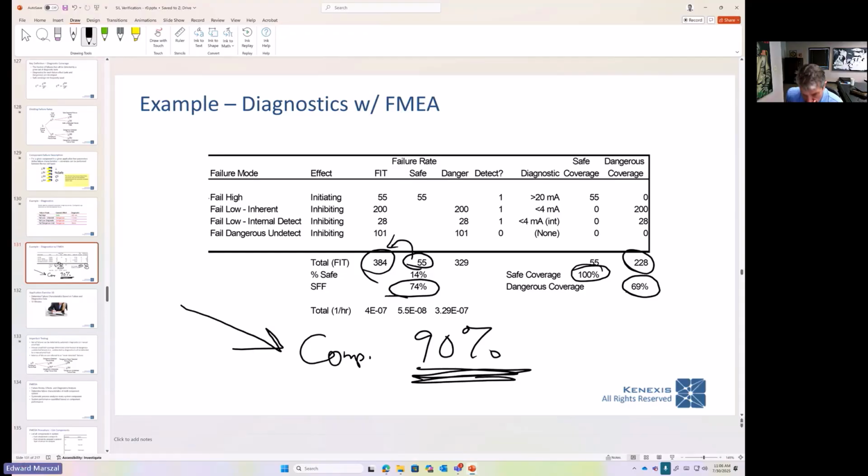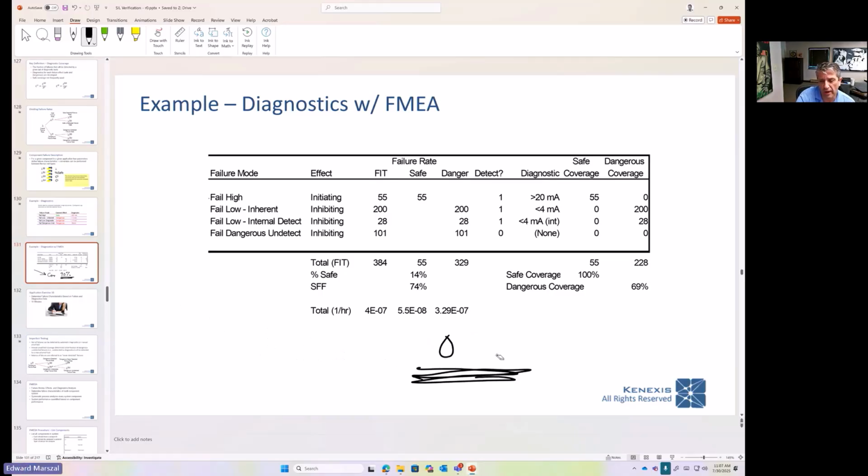Okay. And the second doubt is in the example of your pressure transmitter, there was only one sensor, a 1 out of 1. Is it possible to have an internal diagnostic with only one sensor? Because in the table that you have shown from the IEC 61508, the input comparison is always talking about 1 out of 2, 2 out of 3, or better redundancy. Could you show this table? In your example, you have only used one sensor, 1 out of 1. With one sensor, could you have internal diagnostic? I guess yes, but I would like to confirm.